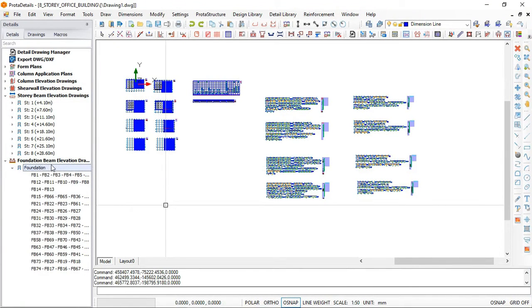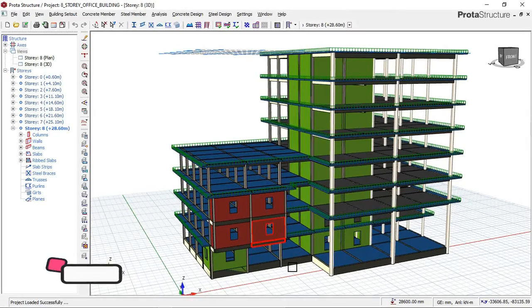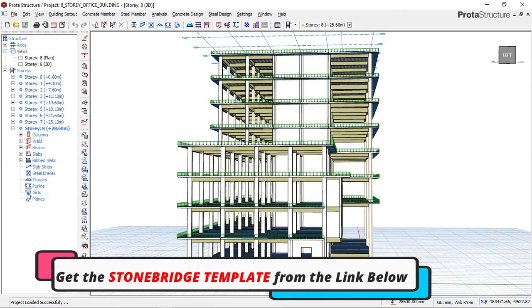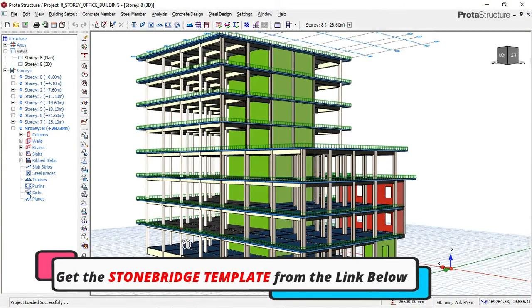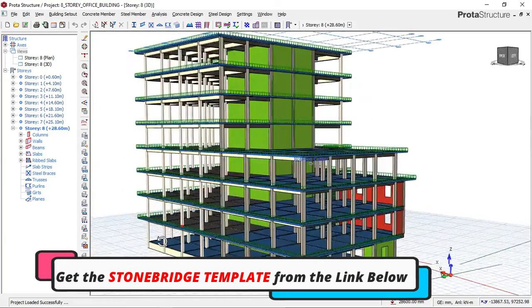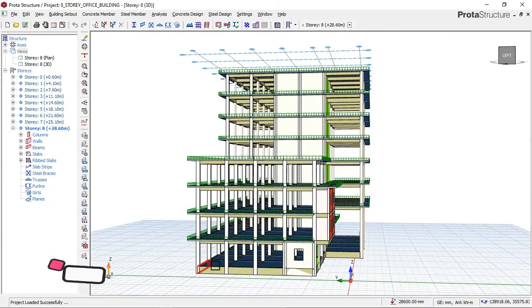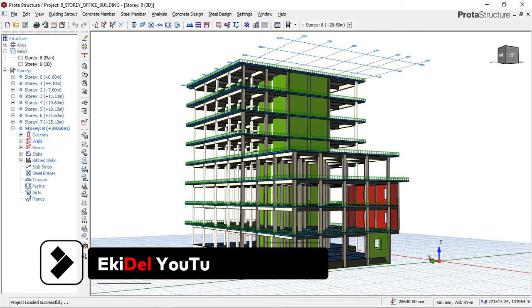By the time we have done the foundation design, because this is a ground beam which was just inserted, and we have not done the foundation design for the piles and all that. This beam was used to connect all this structure together, because this building is to be designed against earthquake. So we have to connect all the columns with beam first, then we use our pile foundation.